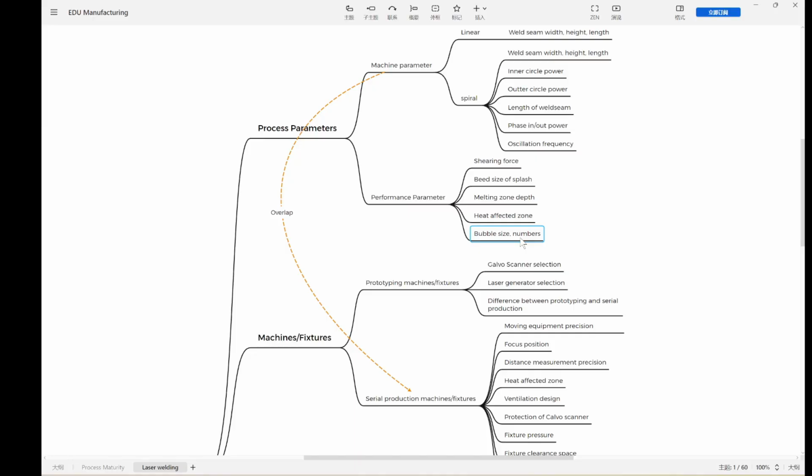If you cut it open, you will see it. This bubble size also affects the conductivity of the current. If the overlapping size or area is not big enough, there could be heat generated, and you may burn the product.